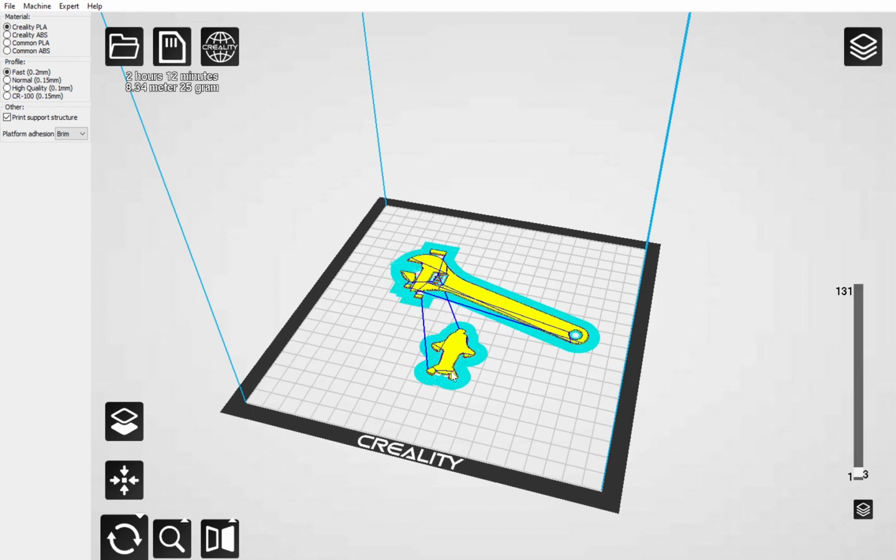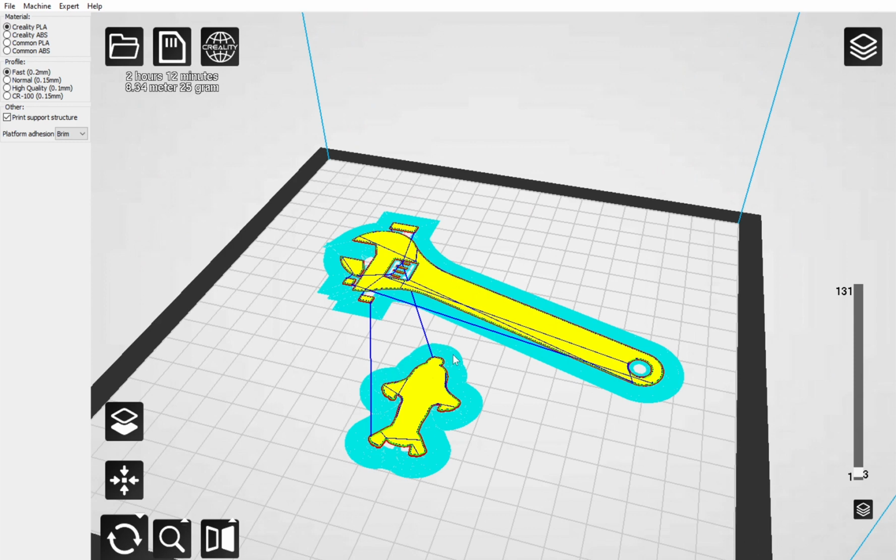The Brim one is where it will add almost like a peripheral layer around your object, and that will ensure that the edges of your object do not start to peel away from the bed. You may find this sometimes with objects when you start to print them. The temperature difference between the bed here at 60 degrees and the nozzle does, and as it cools, it does start to cause some peeling away of the object. And the Brim support structure here is being designed or introduced to try and inhibit that from happening. So that's what that does.